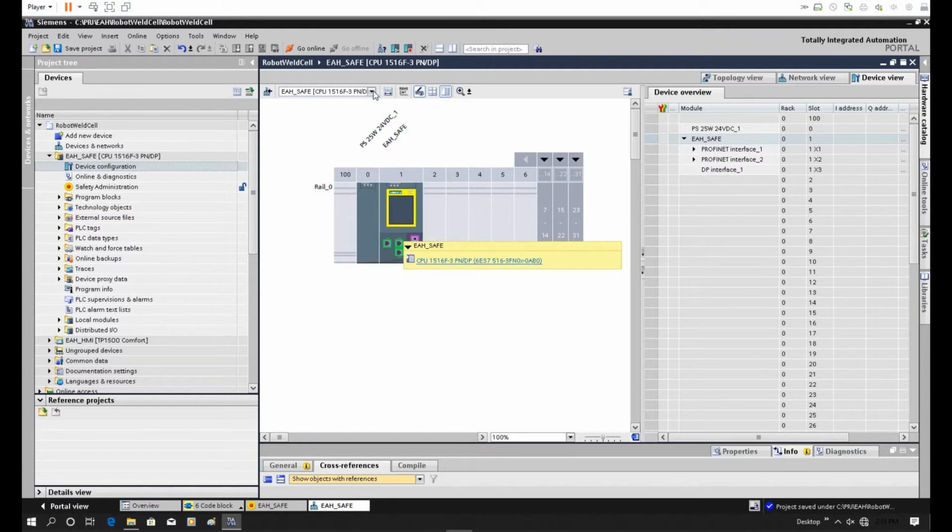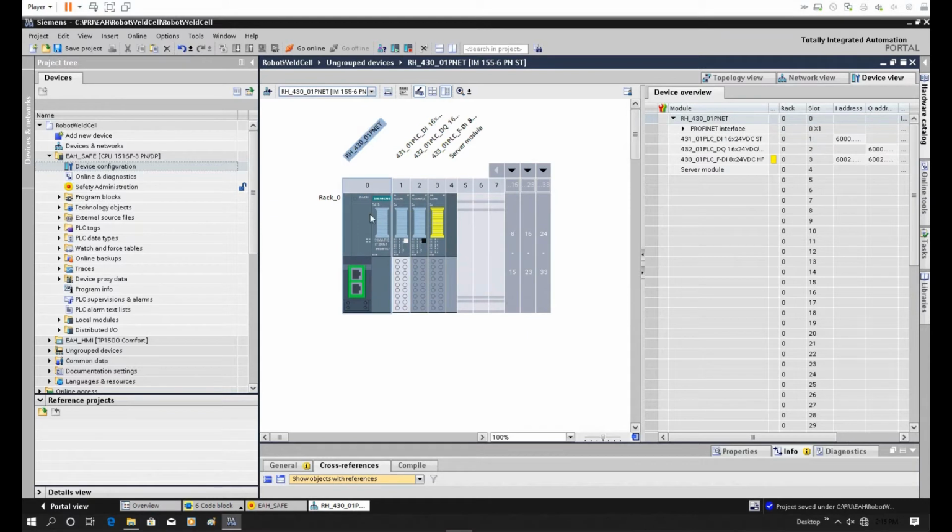The typical style will be like this. That is the ET200SP remote station. That is an interface module, and this interface module has two Profinet communication ports. It includes the standard input and output, as well as the safety input and output. It's quite flexible. You can configure it based on the safety devices and the sensor allocation.